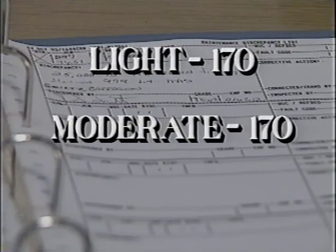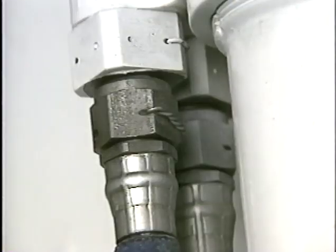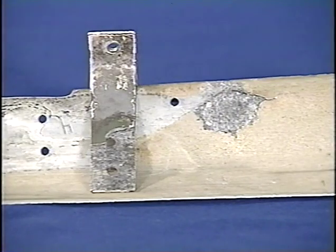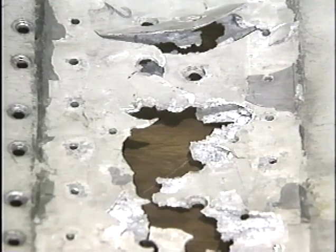We mentioned earlier about entering the degree of corrosion in the forms. There are 3 degrees of corrosion that are identified in TO 1-1-691. They are light, moderate, and severe. This example of light corrosion shows minor pitting and discoloration. Moderate corrosion may show evidence of flaking and scaling, along with some paint blisters. The pitting can be as deep as 0.010 of an inch. Many of the same characteristics of moderate corrosion exist in severe cases, with the addition of intergranular corrosion and exfoliation.